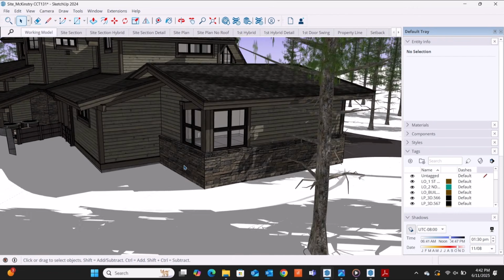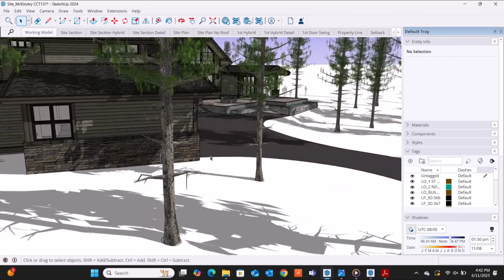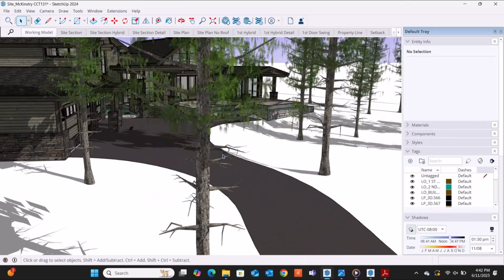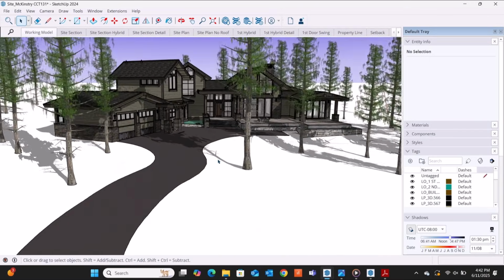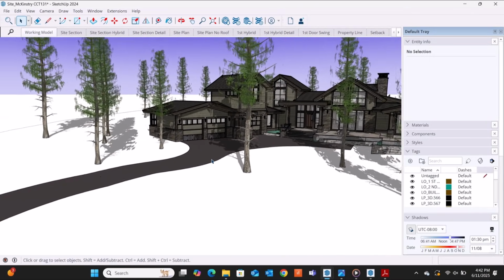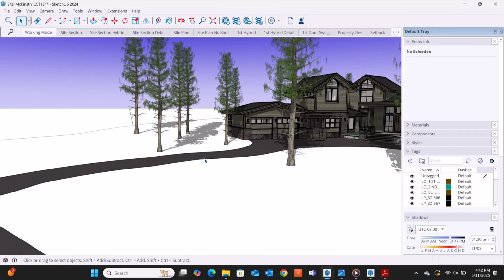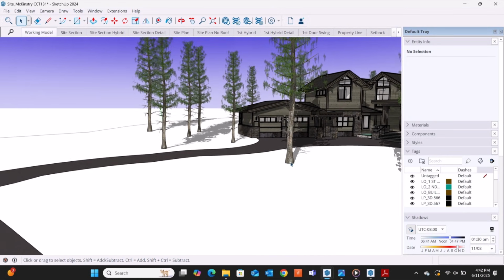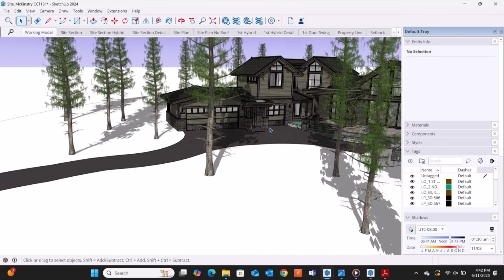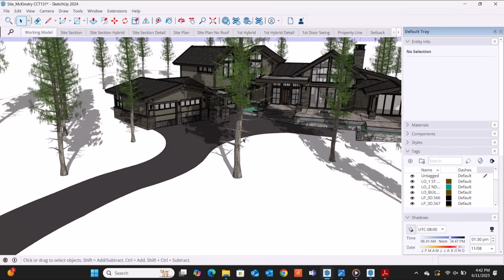And this house, they were lucky. The driveway is really not very steep. I think we've got, for the most part, 2% everywhere, even down through here. I think we have just a 2% cross slope, and then this slope's at 3-to-1.